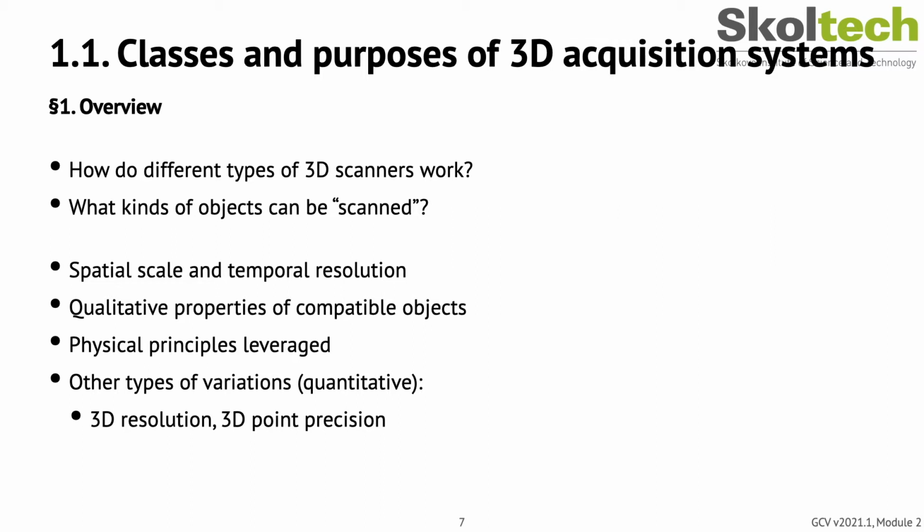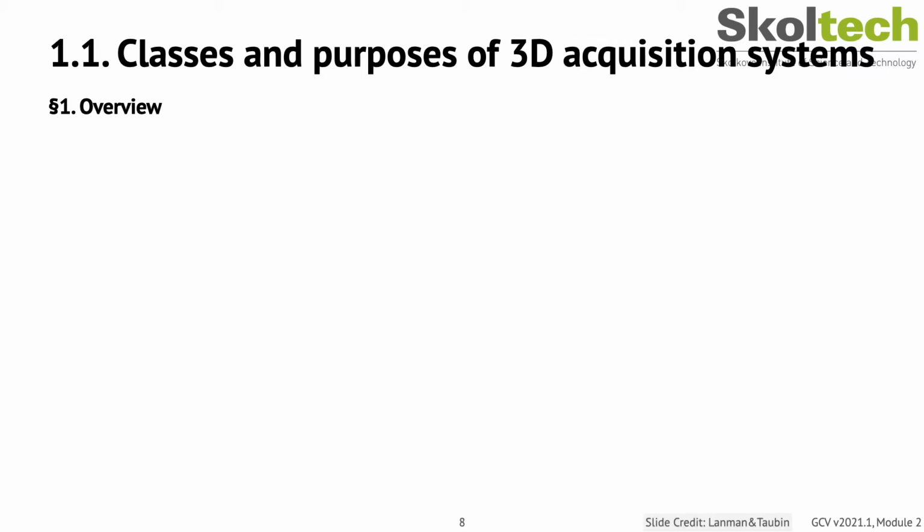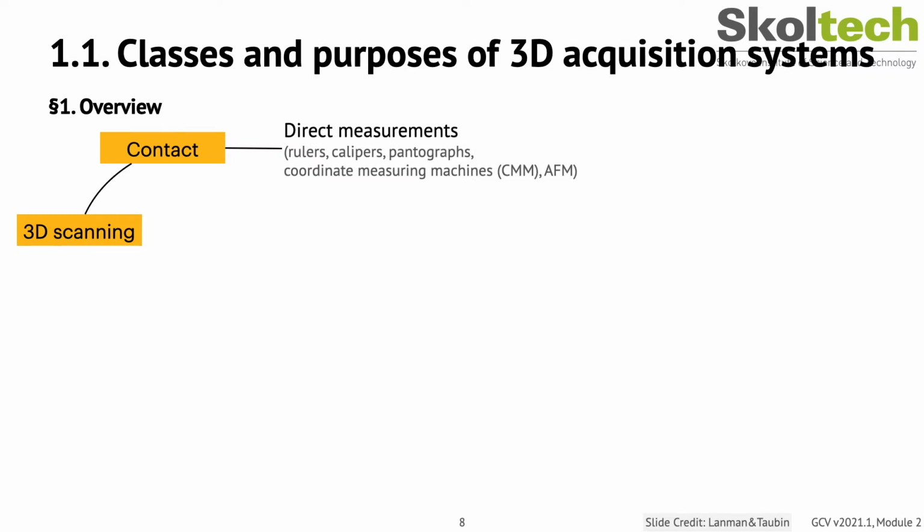Let us build a small taxonomy of 3D scanning machines, inspired by a conventional classification by the pioneers Brian Curless, Douglas Lanman, and Gabriel Taubin. A variety of technologies exist for digitally acquiring the shape of 3D objects. Contact 3D scanners probe the subject through physical touch, while the object is in contact with or resting on a precision flat surface plate. Where the object to be scanned is not flat or cannot rest stably on a flat surface, it is supported and held firmly in place by a fixture.